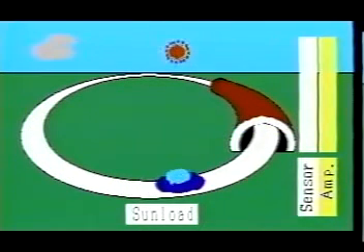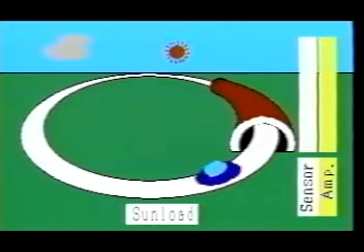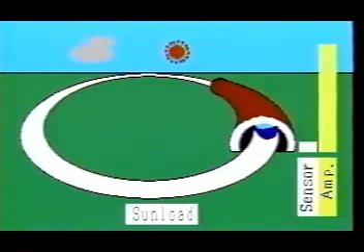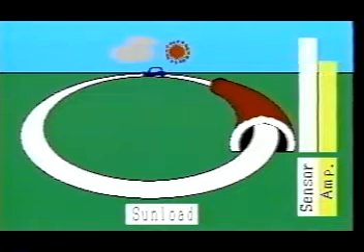Let's look at what happens when the car goes through a tunnel. The amount of sun load detected by the sun sensor suddenly varies. The output signal from the sun sensor to the automatic amplifier will be delayed to prevent the automatic air conditioner from making a sudden change in normal operation.